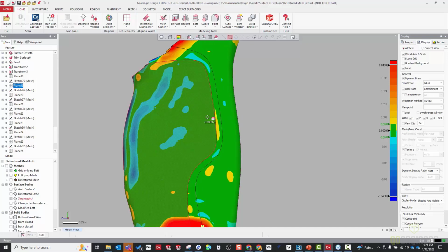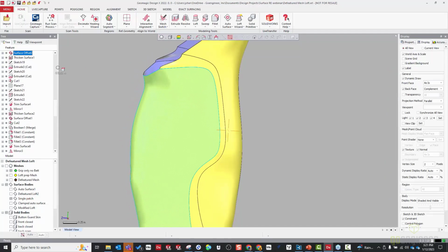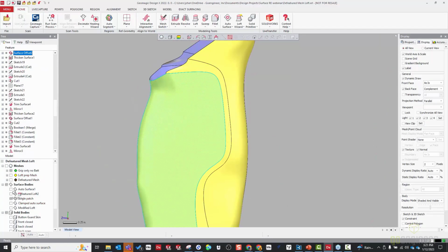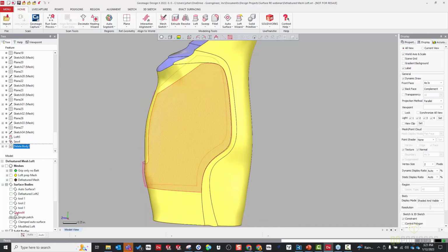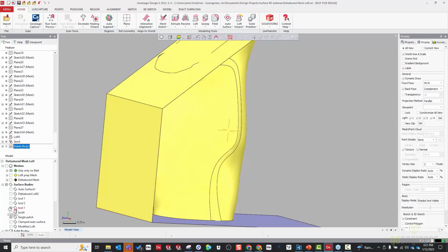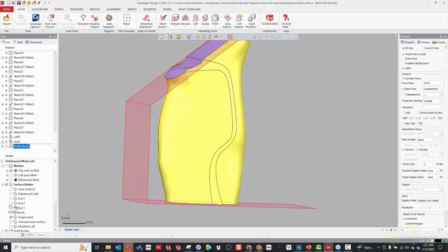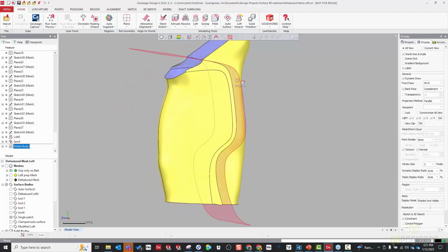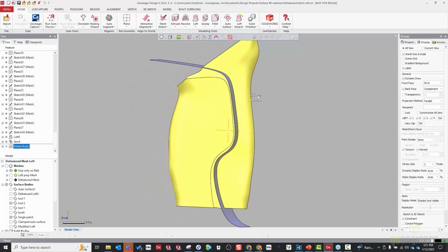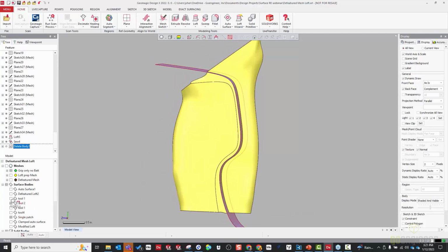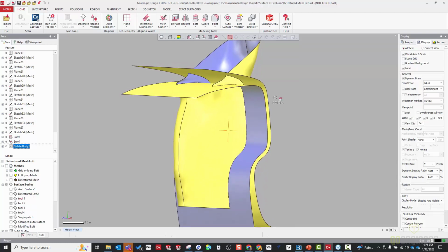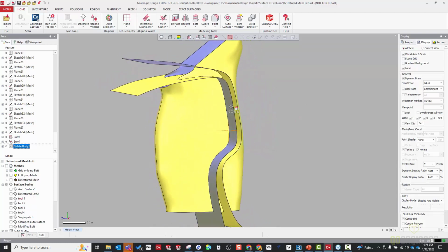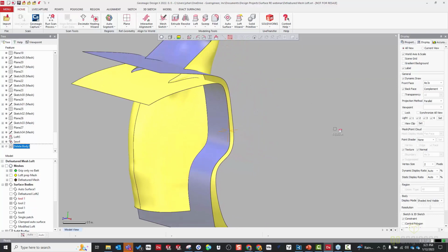And well, let me just show you how I trim this together. So I have some different, let me go back and show you some of my tools. So here we had some different surfaces I used to trim this. Here's one surface I used to cut one of my single patches into this shape. Then here's the other. And so these are just simple sketches that I extruded, and those sketches are fully parametric. These extrude operations are parametric.